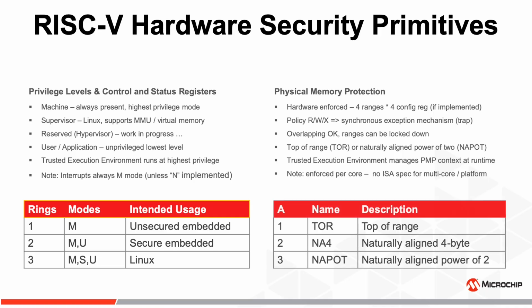And what can be done is to define a number of contiguous memory spaces. And this is not just about securing memory, this is about securing any memory mapped resource, including all the peripherals and any kind of data that is accessible through the interconnect to the bus. And whenever there is a policy enforced there, a value loaded up, well, the system in real time, the hardware, checks whether the policies are respected. Otherwise, there is an exception. So this is as solid, as resilient as you can get, because it's really delivered by basically a set of gates, to make it very simple.